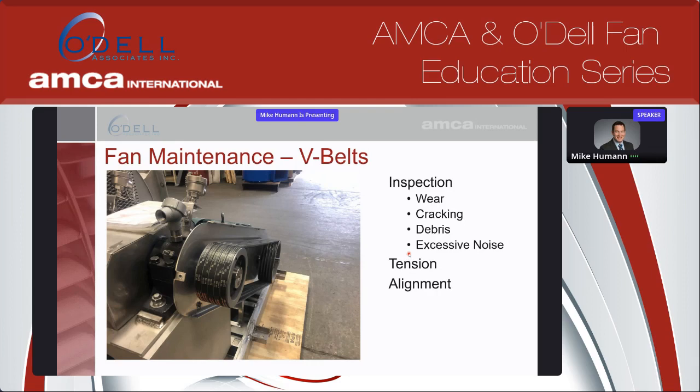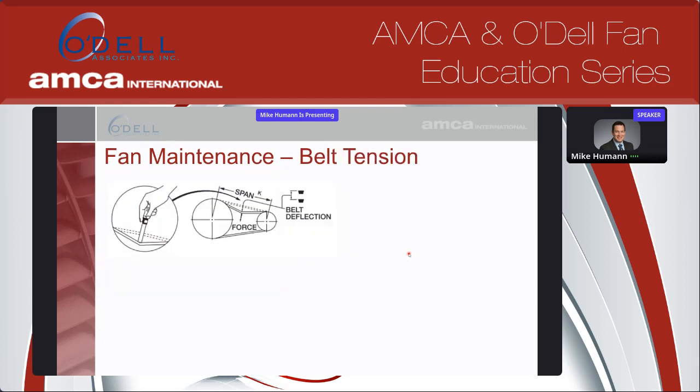Other big considerations in V-belts are tension and alignment. So we talk about belt tension. This is critical to help maintain longevity of belts. You don't want your belts too loose or too tight. This is back to the lubrication: you want to find the right spot. Any belt selection is given with a tension required. It gives you a deflection value and a force value.